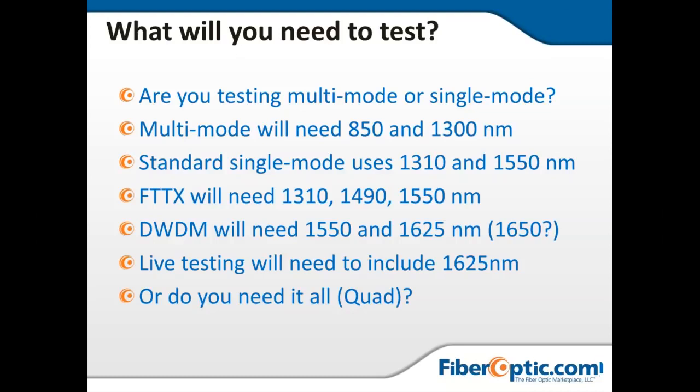But we also want to use this second wavelength as a way of creating a reference for a macro bend. One of the big problems we have with fiber is bending of fiber. We get loss or attenuation, okay? Normally, the higher the wavelength, the better it will perform with fusion splice loss and things of that nature. But it's inversely related when it comes to bending. The higher the wavelength, actually the more attenuation we'll get when you bend it.